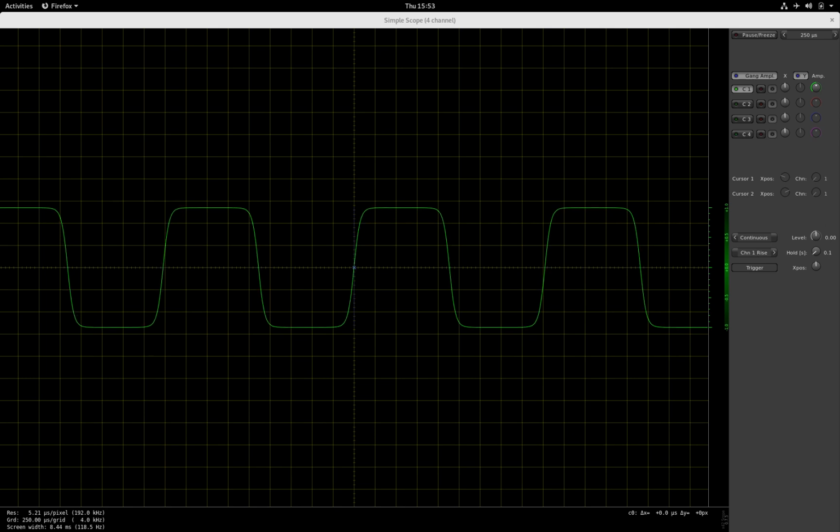And as we continue to increase the gain, the signal through the zero crossing will get steeper and steeper, and the signal will get more and more squashed onto basically the limit, the supply voltage of the effects unit. But the signal will always keep the characteristic of symmetry.